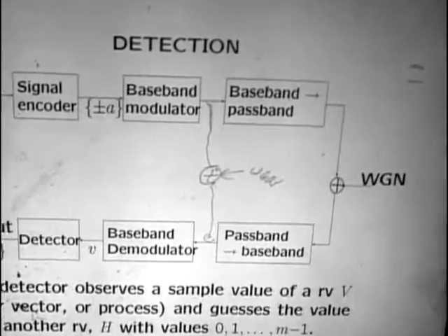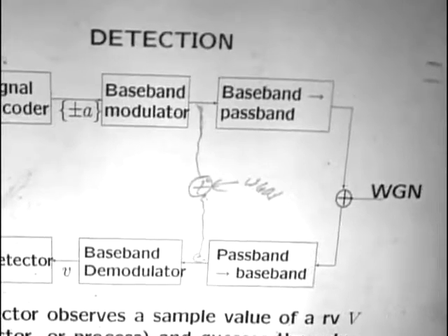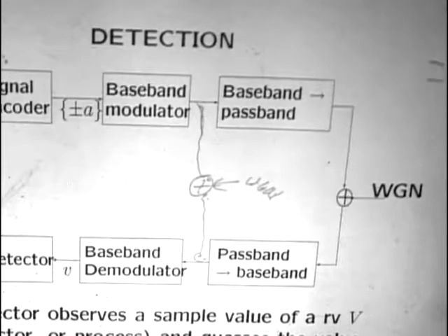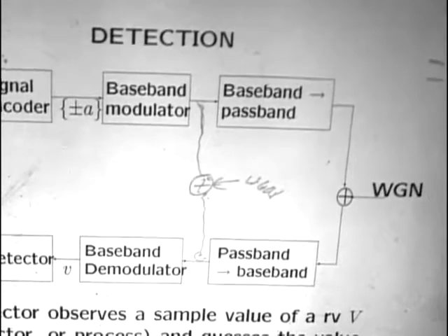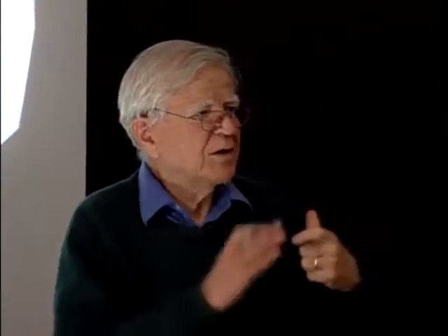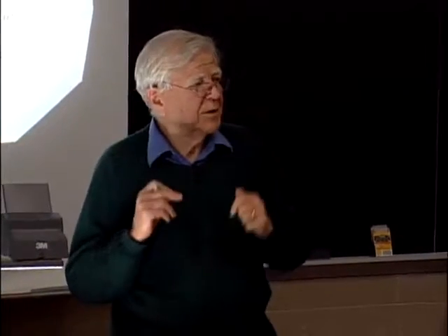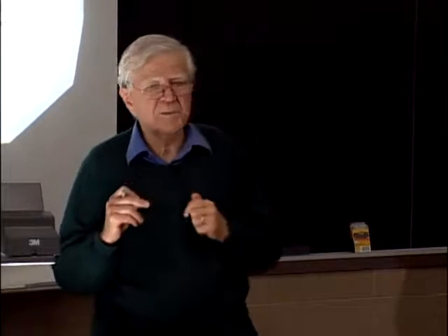We said a neat thing to do was to use a square root of Nyquist pulse at the transmitter. When you use a square root of Nyquist pulse at the transmitter, what you have is orthogonality between the pulse and all of its shifts. Well, now we don't much care about the orthogonality between the pulse and all of its shifts because we're only sending this one bit anyway. But it sort of looks like we're going to be able to put that back in a nice, convenient way.